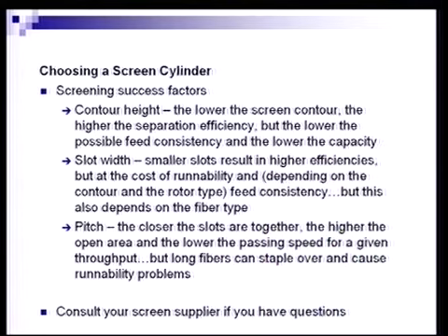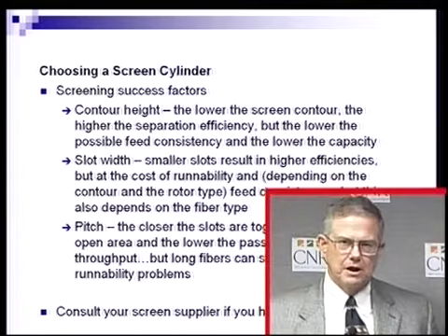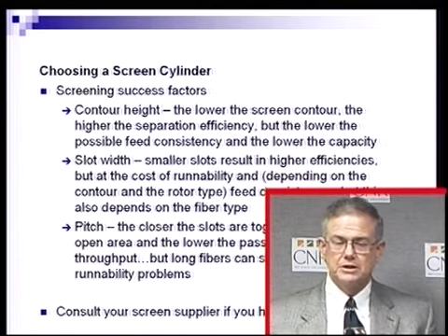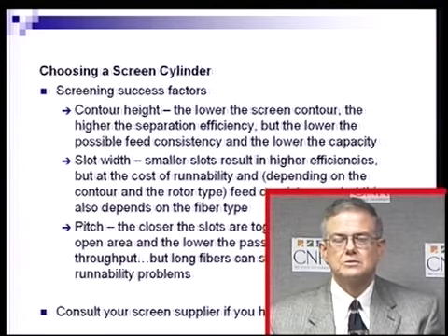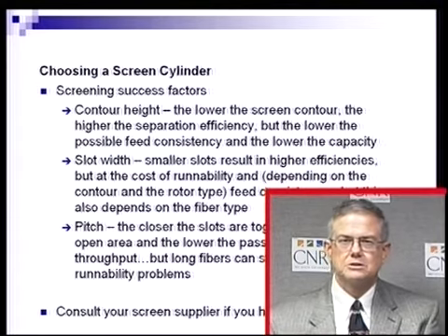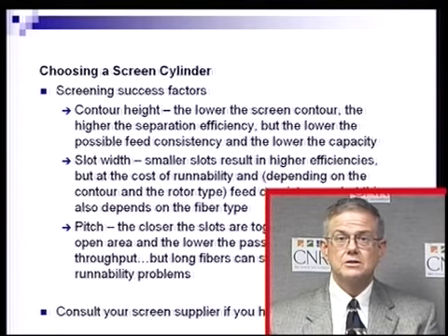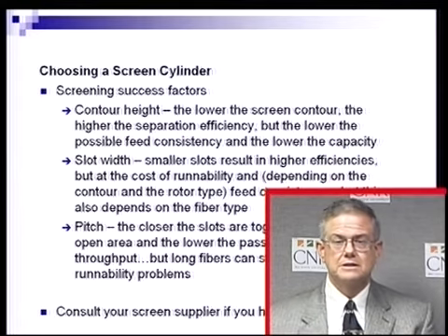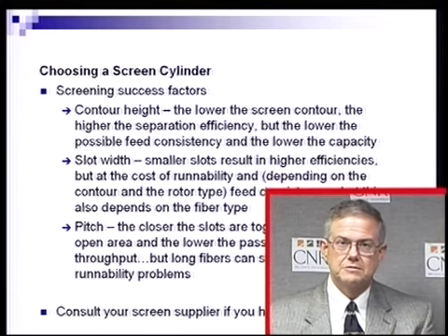And then lastly would be pitch. That is, how close can we put the slots together? The closer the slots are together, the higher the open area and the lower the resulting passing speed for a given capacity. And this is a very good thing. So if we can increase the open area by giving a smaller pitch, or that is a narrower pitch to the wires or a narrower pitch to the slots and how closely we can put them, then we can increase the open area, increase the capacity, and without sacrificing the efficiency.